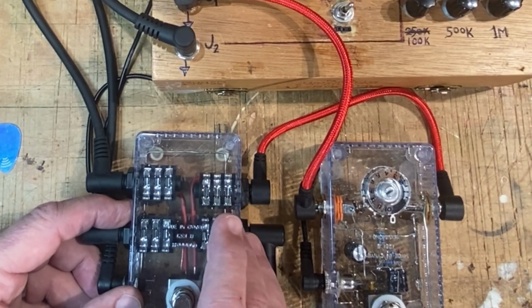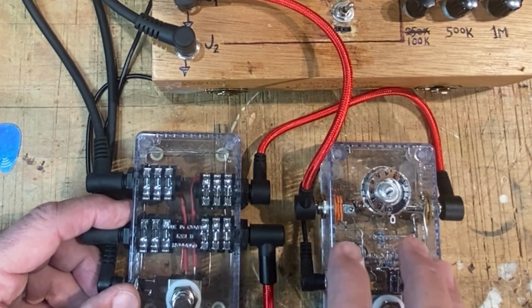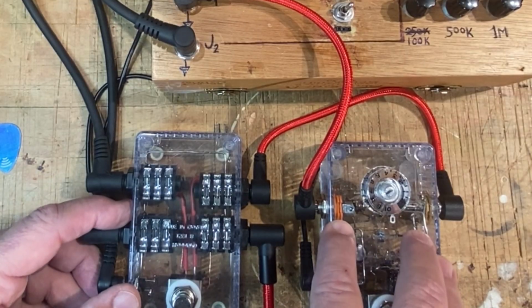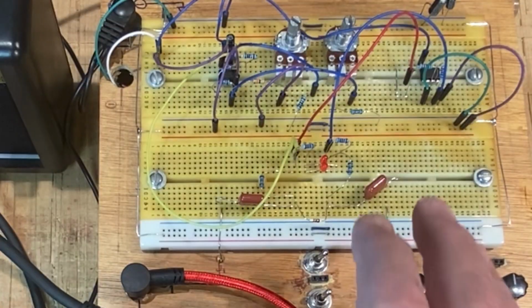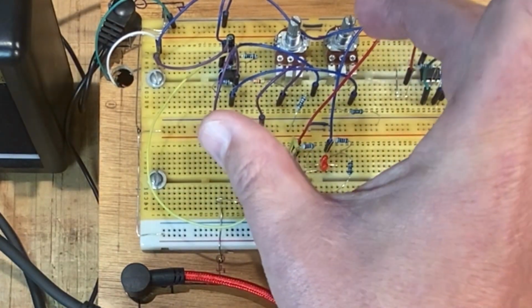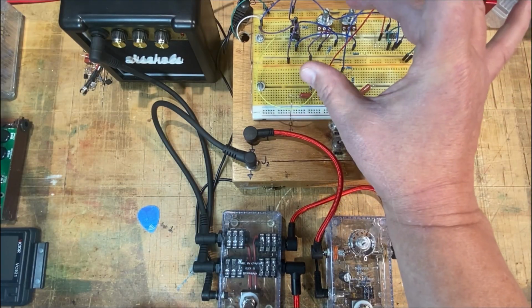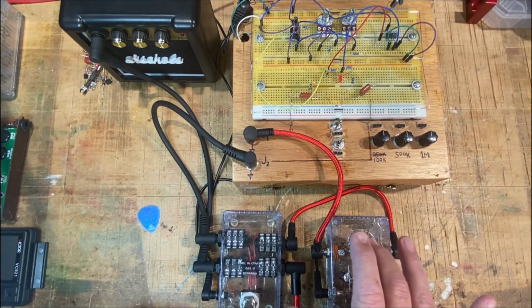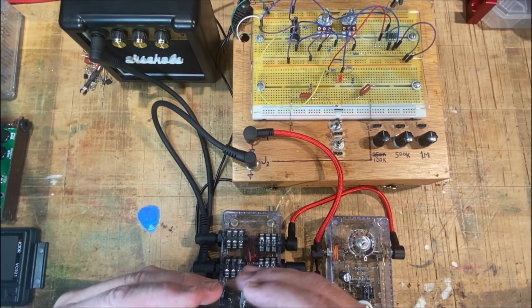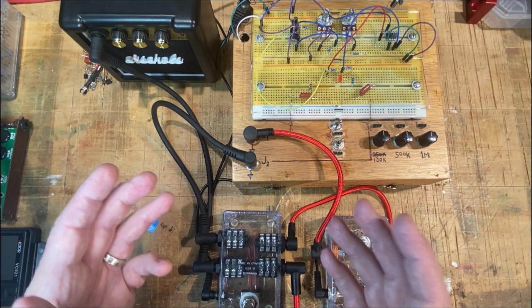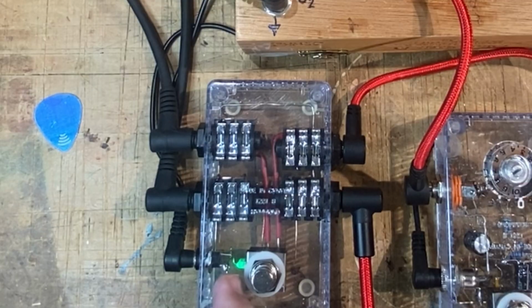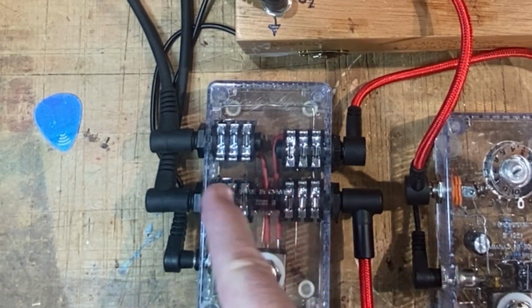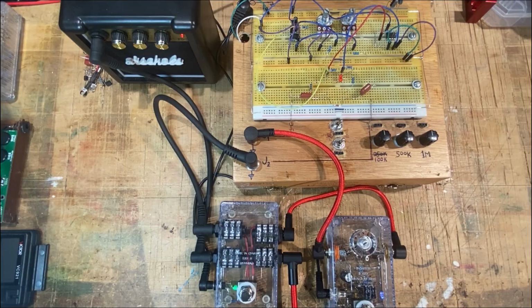I've also added my hardware bypass switch and my 20 dB boost. So the audio signal from the guitar is going to get boosted and then it'll interact with the LFO circuit here. The amplitude of this is high enough that I needed to boost the guitar signal so that they would interact properly to give us the right effect. So here is my clean signal. You can see my green LED here letting me know that the guitar signal is coming straight through and off to the amp.